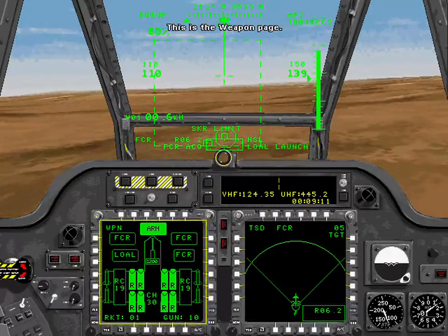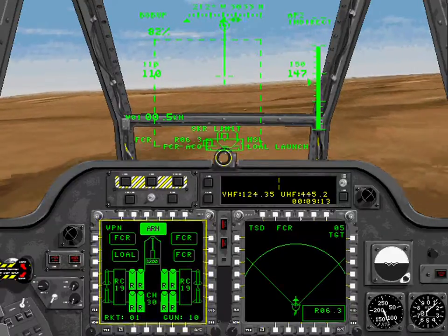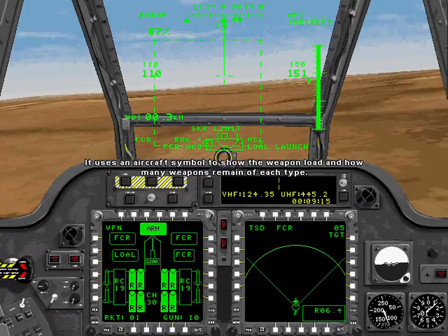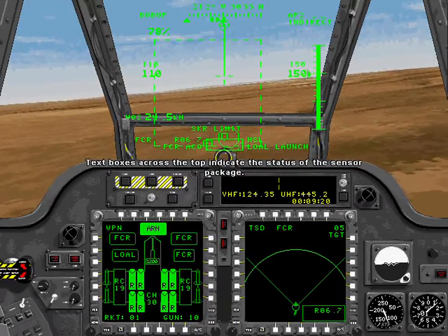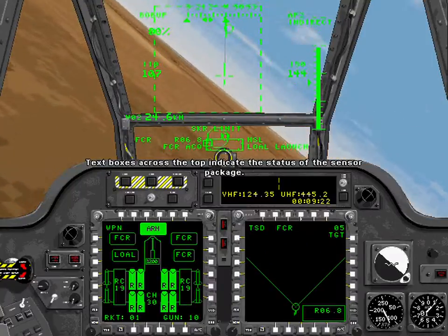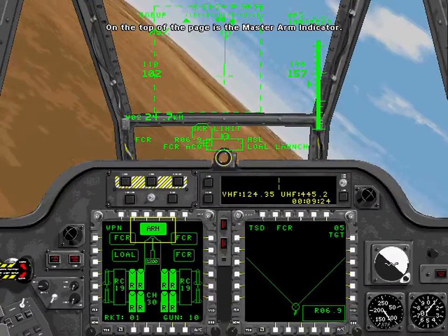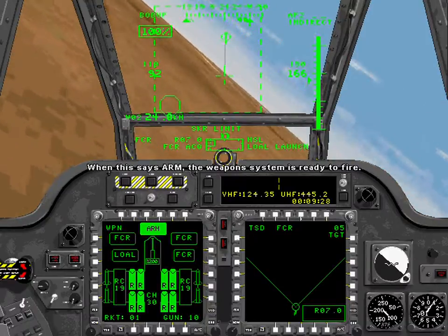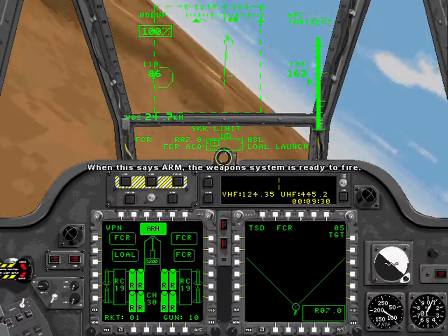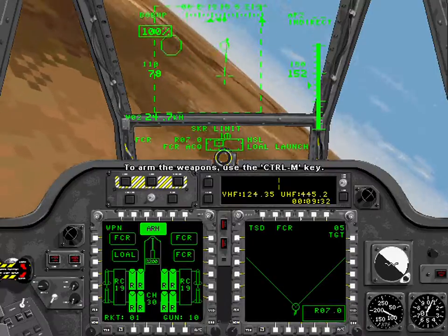This is the weapon page. It uses an aircraft symbol to show the weapon load and how many weapons remain of each type. Text boxes across the top indicate the status of the sensor package. On the top of the page is the master arm indicator. When this says ARM, the weapon system is ready to fire. To arm the weapons, use the...